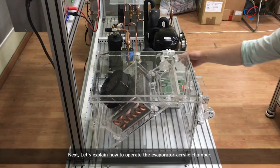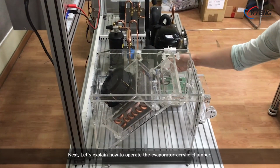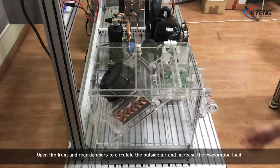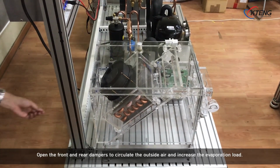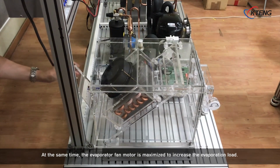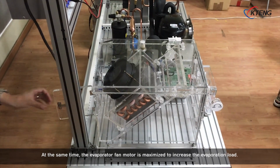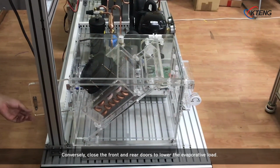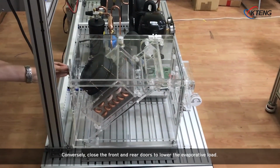Next, let's explain how to operate the evaporator acrylic chamber. Open the front and rear dampers to circulate the outside air and increase the evaporation load. At the same time, the evaporator fan motor is maximized to increase the evaporation load. Conversely, close the front and rear doors to lower the evaporative load.